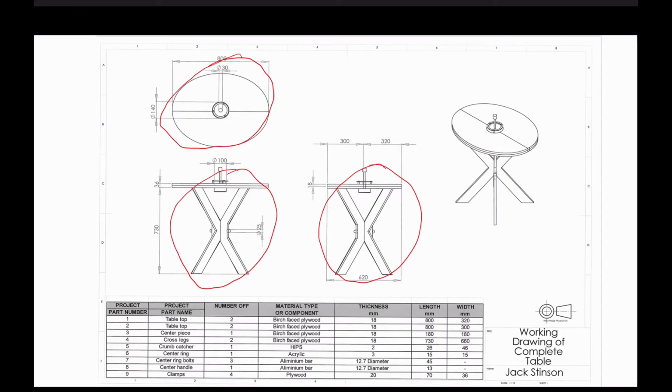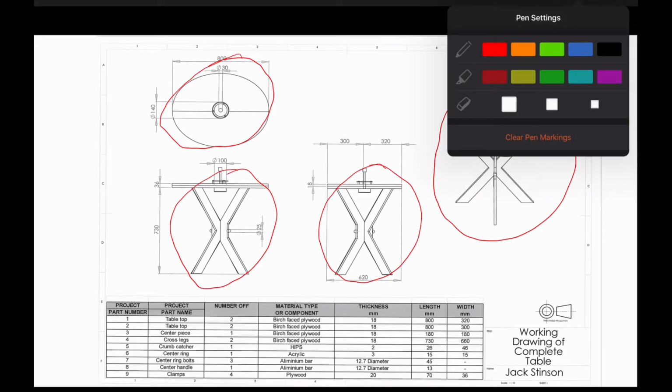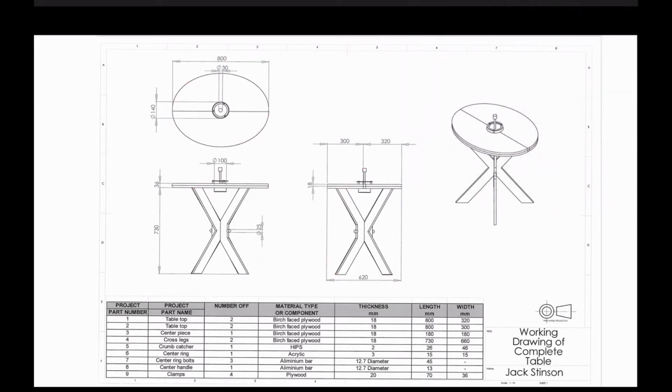Usually in a working drawing then you would give a pictorial view, a 3D drawing, so that the person who's looking at the drawing gets a more realistic view of the overall product. So what we're looking at then is those three views on the left hand side. Now they must be in this position: plan view, front view, side view,